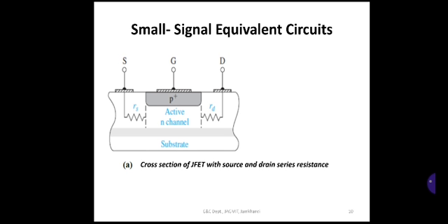This equivalent circuit introduces frequency effects in the transistor through the equivalent capacitor and resistor circuit. Therefore, the various physical factors in the junction field effect transistor that affect the frequency limitations will be considered, and a transistor cutoff frequency, which is a figure of merit, will also be defined later. First we'll discuss the small signal equivalent circuit.